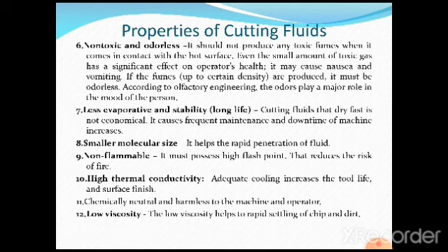If the viscosity is less, what happens? It will allow the metal chips to fall down very easily into a tray when it is made to flow in the cutting zone during the machining process. So these are some of the desirable properties that we expect from any type of cutting fluid.